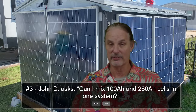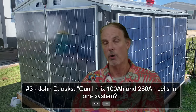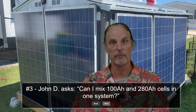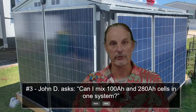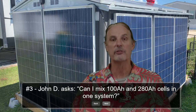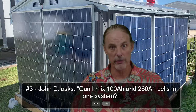And if the battery is not designed to handle that, it could cause problems. Most of them will also tell you that you can only have so many in parallel. The reason for that is the same thing: they don't want to see that transfer of power from battery to battery cause issues with the BMS. Thus, my reason for everything needing to be appropriately fused, to keep them isolated and safe from all the other batteries.